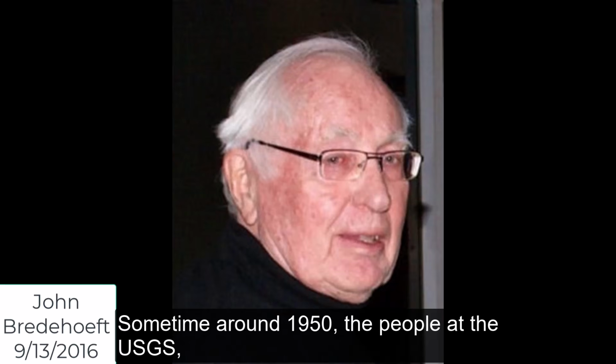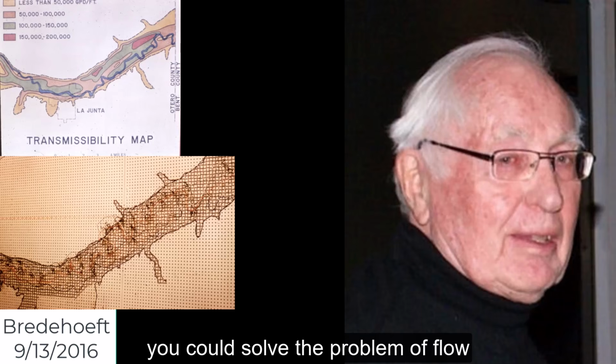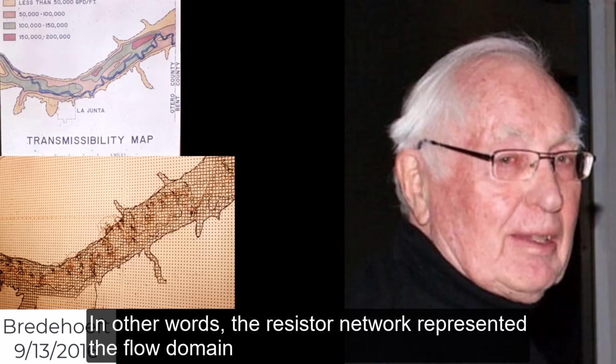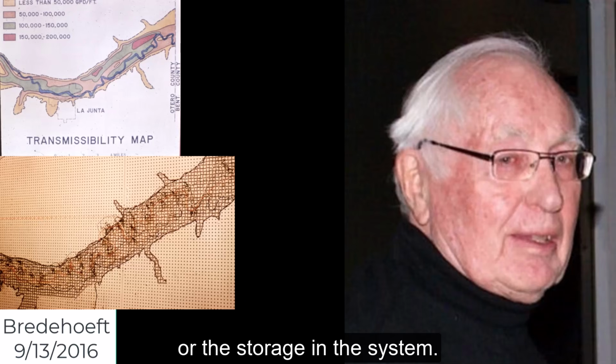Sometime around 1950, the people at the USGS, particularly Bob Bennett, realized that you could solve the problem of flow using a resistor capacitor network that represented the aquifer and the storage coefficient. In other words, the resistor network represented the flow domain, and the capacitor network represented the domain of the capacitance or the storage in the system.